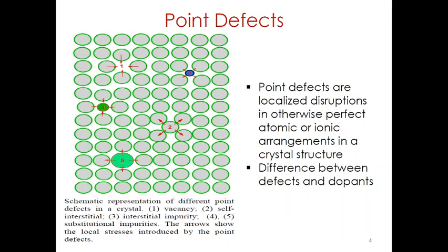These imperfections may be introduced by movement of the atoms or ions when they gain energy by heating during processing of the material or by introduction of other atoms. The difference between an impurity and a dopant is as follows. Typically, impurities are elements or compounds that are present from raw materials or from processing. For example, silicon single crystal grown in quartz crucible contains oxygen as an impurity.